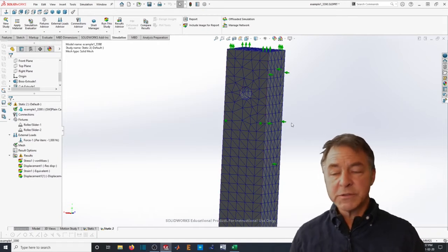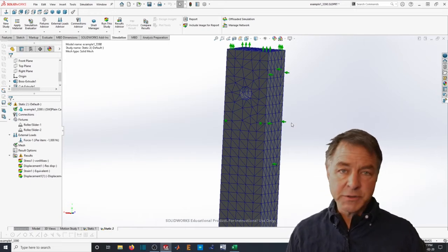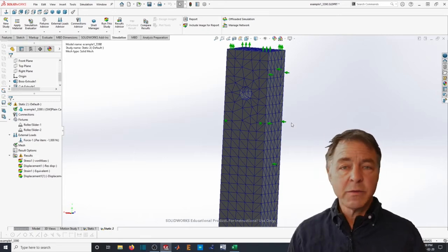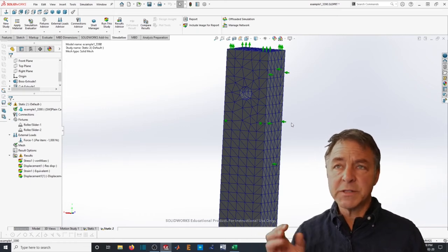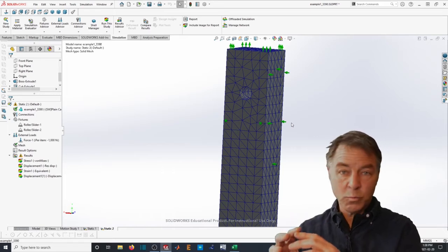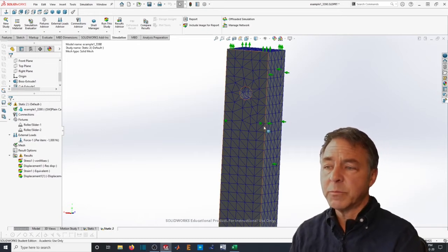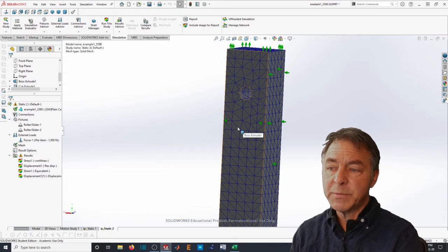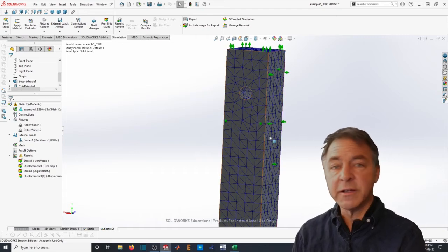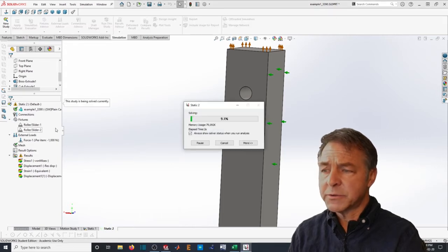Now, you know from the previous video that the way this tool is going to solve the deflections and the stresses is it's going to do a matrix inversion of a very big matrix. One of the powerful things in the solution method is that a lot of what we've changed in the model is very localized in that matrix. So it's a small subset of the matrix that represents these grid points, because each of these tetrahedrons is one of those weighting factor W's that I described in the previous video. So let's see how this goes. Run the model,